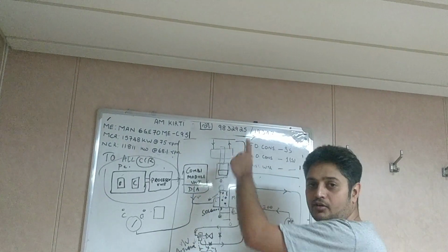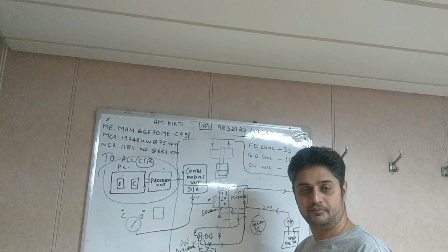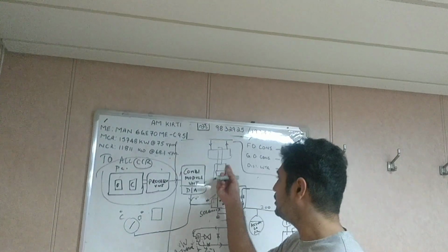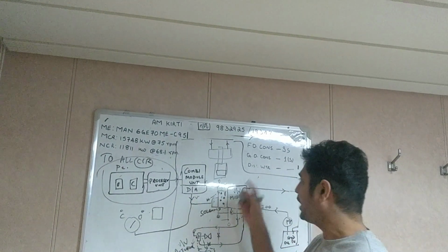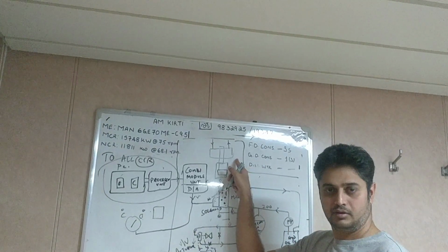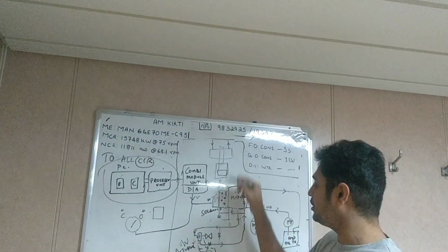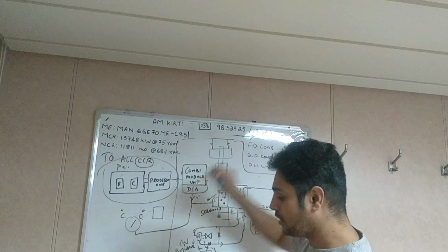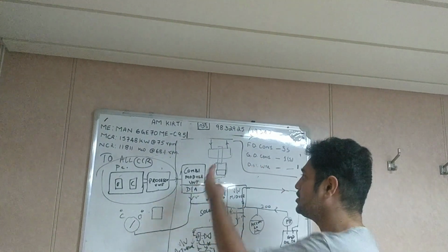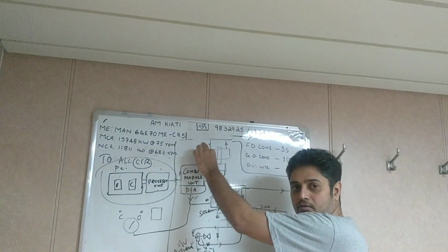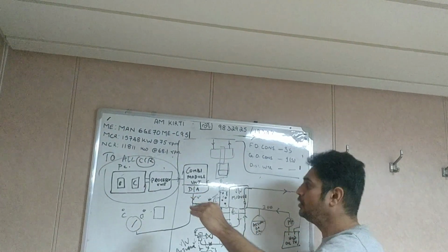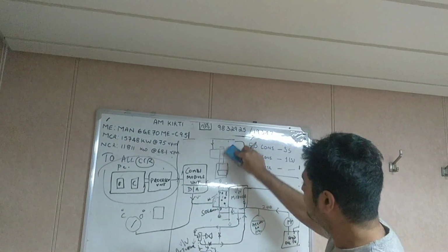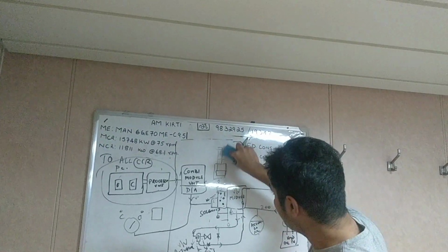But if the actuator is moving, it means the actuator is free, because the actuator is the one which is turning the valve. So if the actuator is free and still the valve is not moving, after removing the actuator, you have already checked, there is free movement of the actuator, but it is not able to turn the valve.